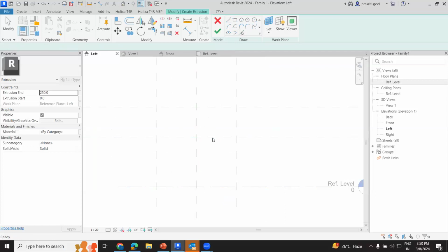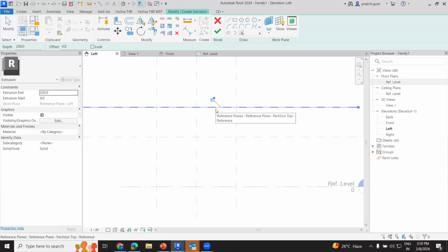And now whenever you develop the sketch, it is preferable to create the sketch using pick line and use reference plane. So wherever you pick the reference plane, you will get this lock system. So this lock system means what? When your reference planes move, your sketch is also moving. So your sketch and your reference plane will be locked. This helps you, when your parameters are changing, your sketch, your geometry is also changing. So this you need to do,